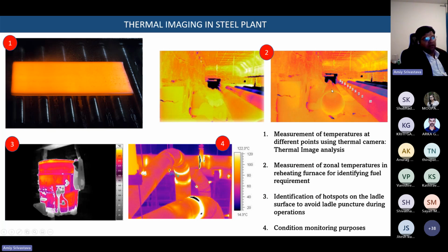If it spends more time in the mill, why? Because the rolling process is taking place gradually, so the tail end is in the atmosphere for more time. In some mills, covers or troughs are not available. The troughs are available, but heat-saving covers are not available. In that case, a lot of temperature is lost from the tail of the bloom.